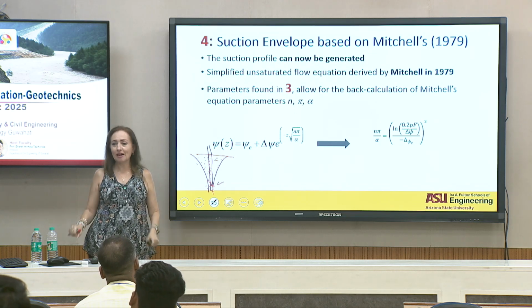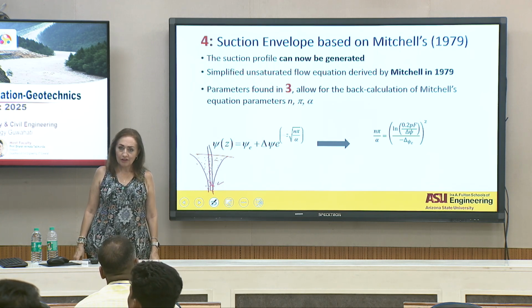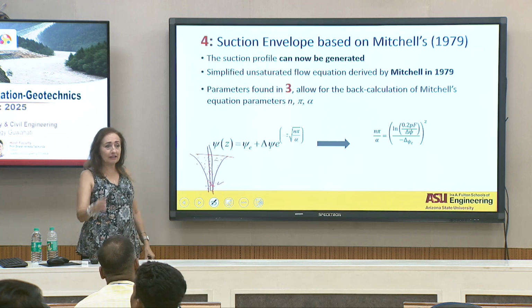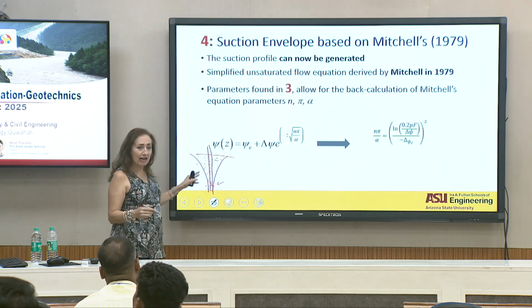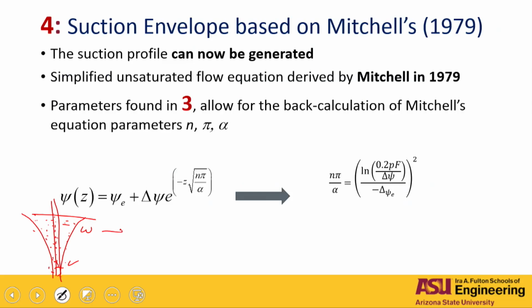Exactly. From the SWCC. This SWCC, did you consider the load effect or is it free? No, we did consider load effect. The question is, okay, how do we go from the water content that we got in the field to the suction values, right? To figure out these envelopes and to be able to calculate those values, right?